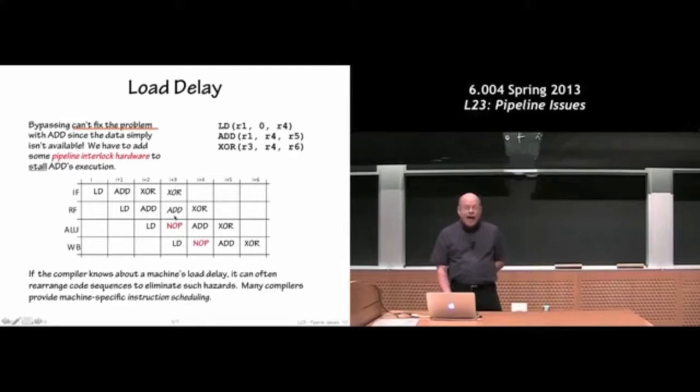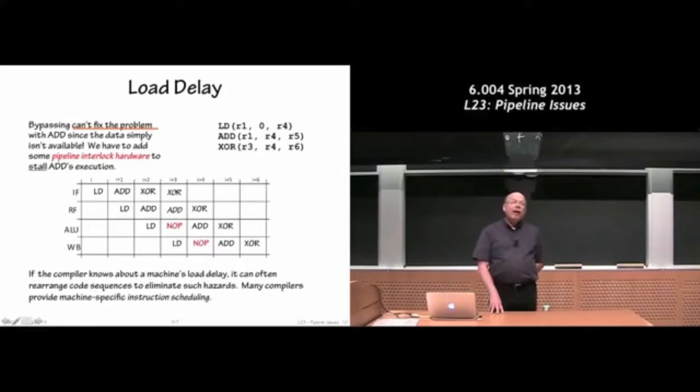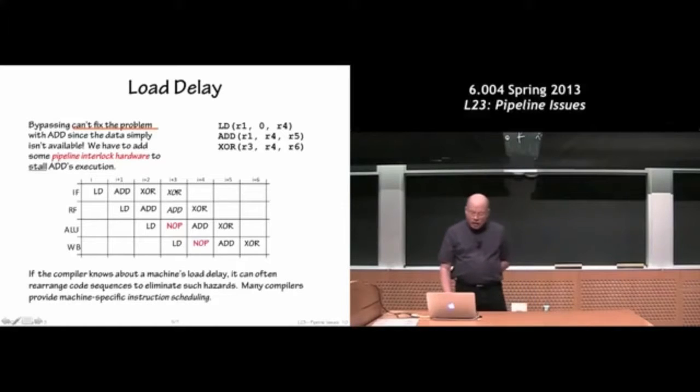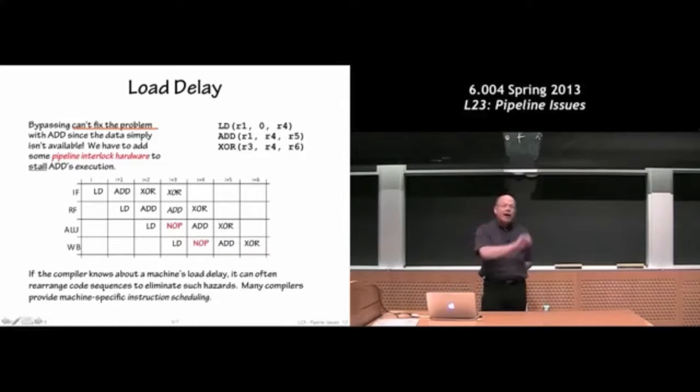And because the add instruction is stuck in the RF stage, the other instructions that come later in the program, or earlier in the pipeline, they come at earlier stages of the pipeline because they're later in the program. They just have to wait in line. They can't move forward either. They're behind us. They have to wait for their turn in the RF stage. I'm sorry, occupado, right? I mean, this stage is occupied.